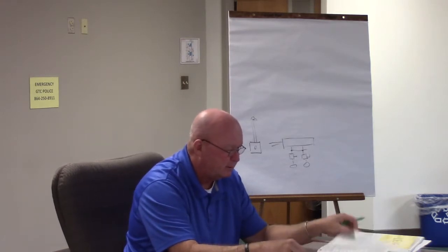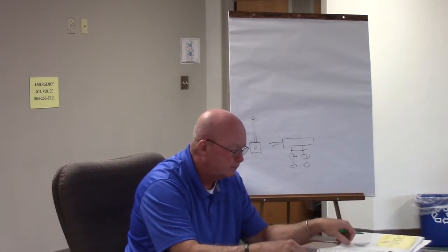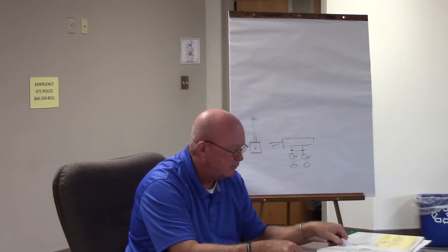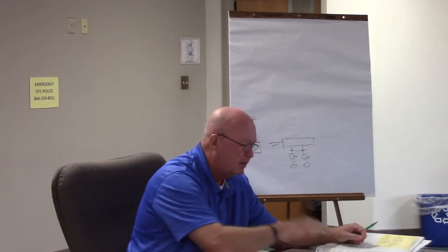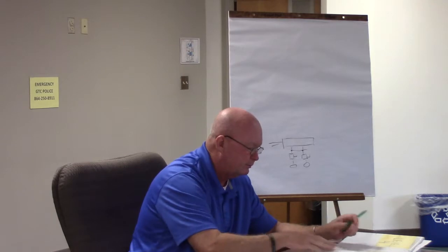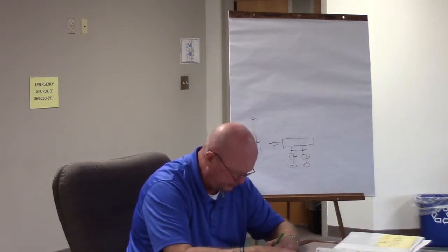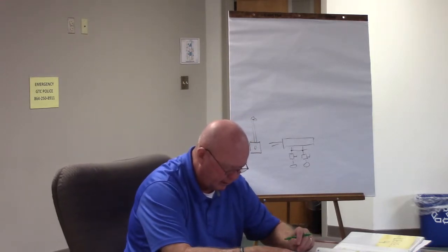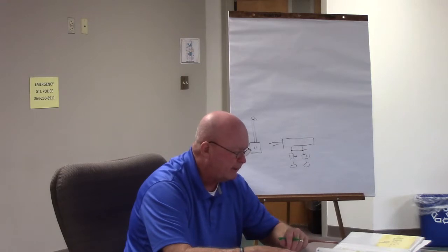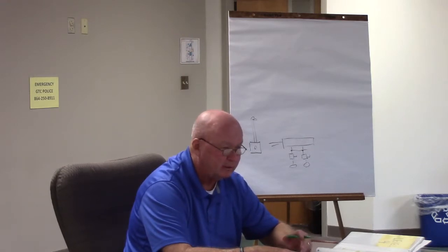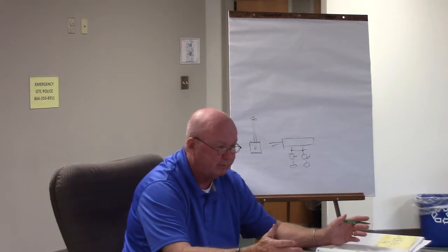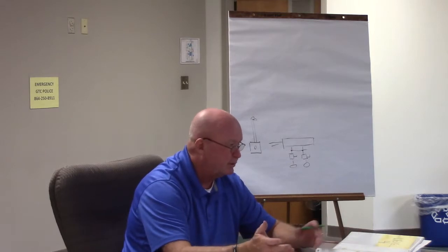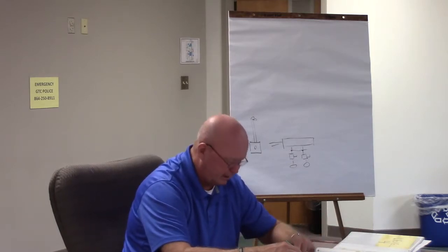Number 14. NEC 220.12 provides specific information for determining lighting loads for occupancies. NEC 220.12, and that's found on page 12. And there's a table we'll get to. Most, like a dwelling, is 3 VA per square foot. And there are other different entities in which it varies, whether it's a restaurant or whatever it is, and we'll see what that table is a little bit later.